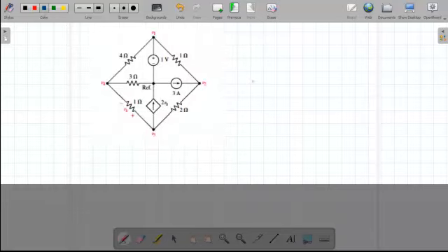So here, we have a voltage source between node 1 and the reference. So from here we can get one equation, and all the others are okay. So we can apply KCL at all of them. First of all, we say V1 equals 1 volt.